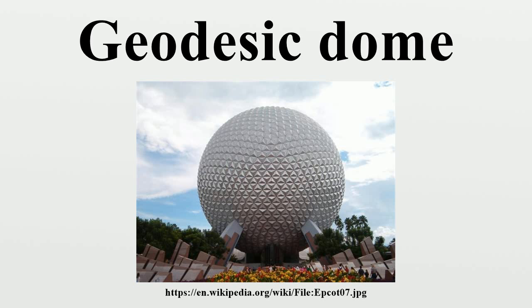Concrete and foam plastic domes generally start with a steel framework dome, wrapped with chicken wire and wire screen for reinforcement. The chicken wire and screen is tied to the framework with wire ties. A coat of material is then sprayed or molded onto the frame. Tests should be performed with small squares to achieve the correct consistency of concrete or plastic. Generally, several coats are necessary on the inside and outside. The last step is to saturate concrete or polyester domes with a thin layer of epoxy compound to shed water.